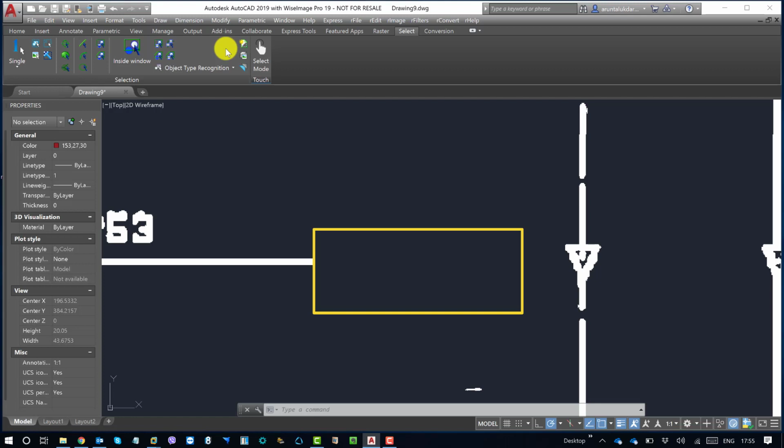The only difference between WiseImage for AutoCAD and WiseImage for Windows selection procedure is to use escape. The moment you select certain objects in the WiseImage for AutoCAD environment, you have to exit from the selection functions, and then you can edit or remove the selected objects.